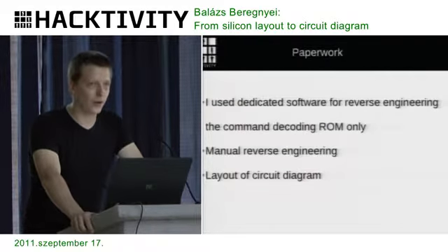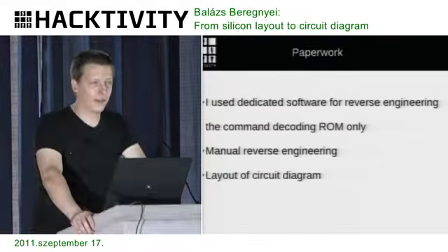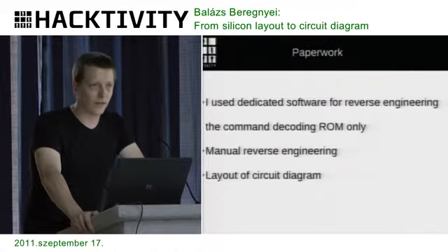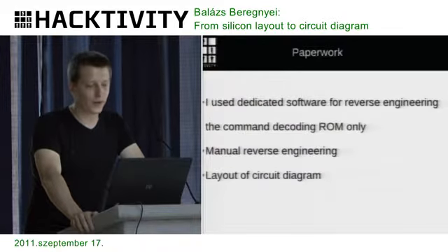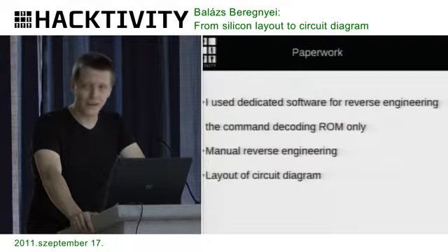Deciphering was mostly paperwork. I printed the entire layout on A4 sheets, and when I found a transistor, I marked it and marked the connections, and once covering the entire layout, I had a very complicated graph. And then I discovered that the whole thing is bad after all, because I marked conduits that had the same information flowing but not in the same phase.